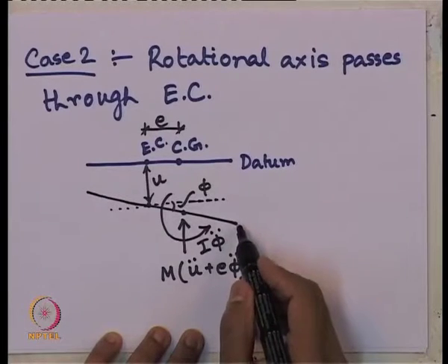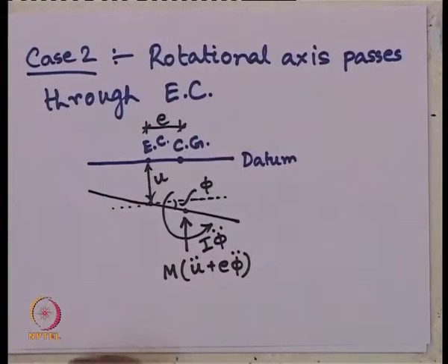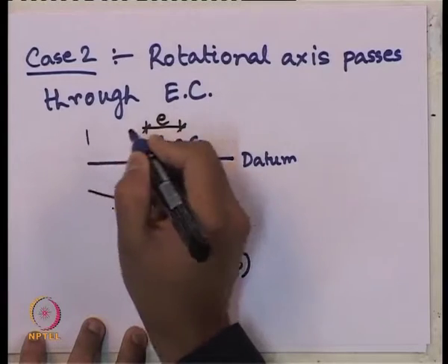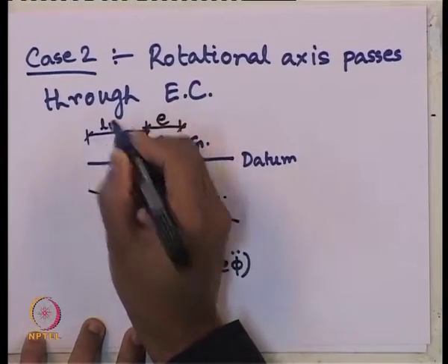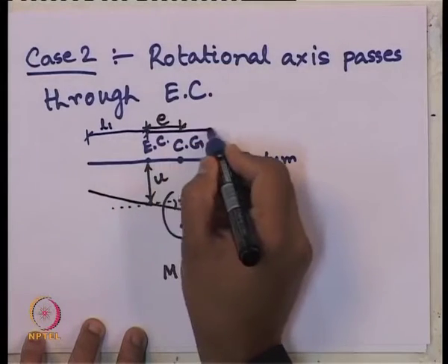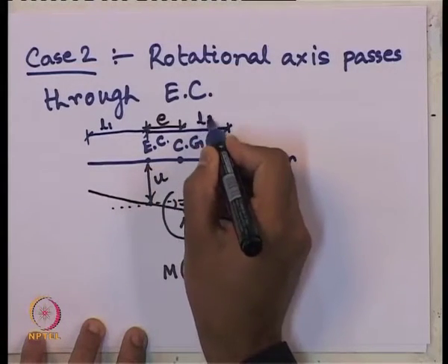And we had springs at these two corners. So, what are the spring forces now acting? Remember, the distance of this spring from the elastic center was L1 from this side and L2 from this side.